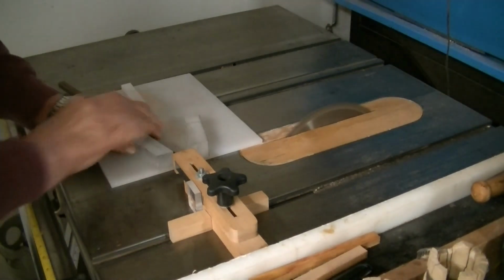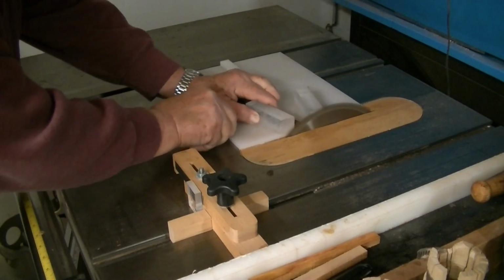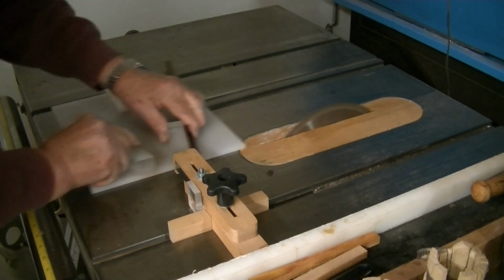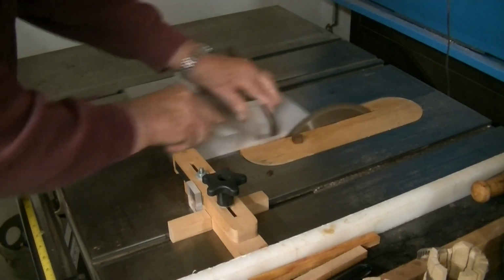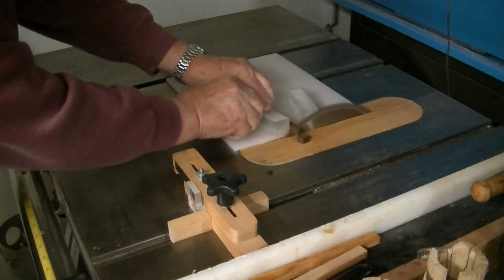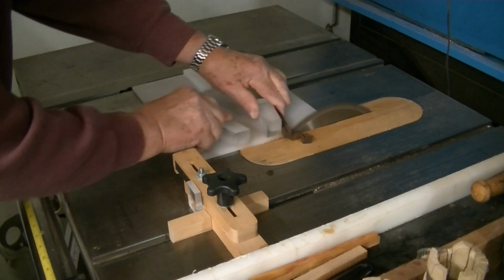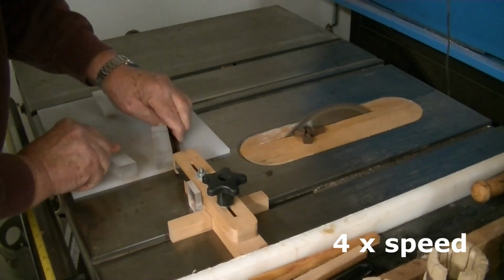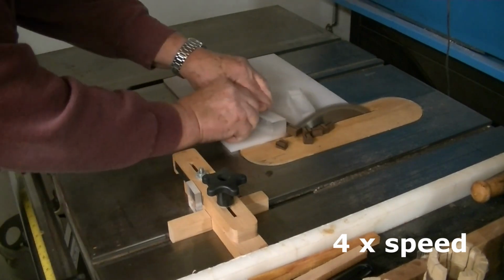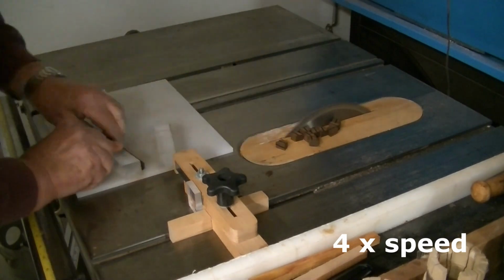So what I'm going to do is to keep one face of the board up, one face forward, trim the end, and without turning the wood, I'm pushing it against the stop, establishing the segment edge length that way. Then back to the second fence to cut the second, and then back to the first to cut the third, and so on. So we'll get through this much faster than I can actually do it. This is the best I can come up with. 12 segments, accurately cut.